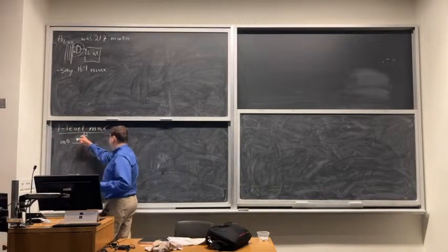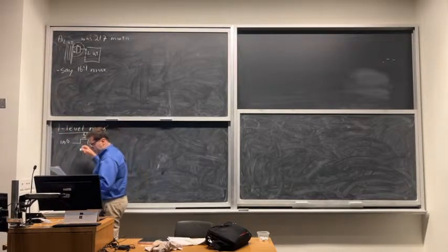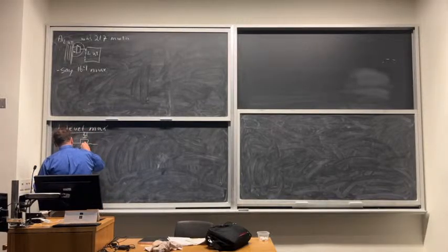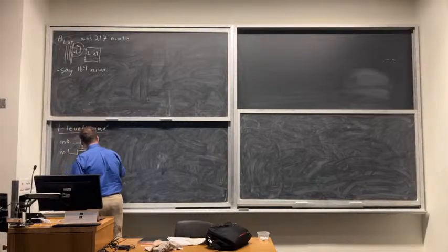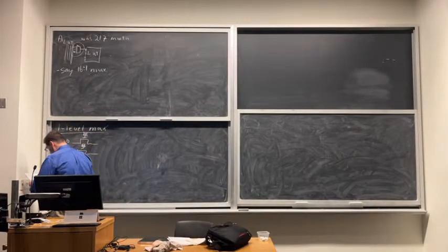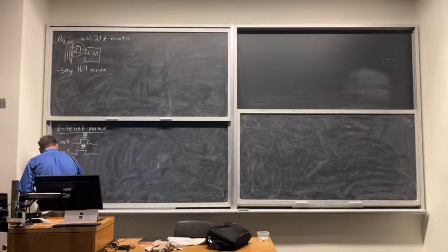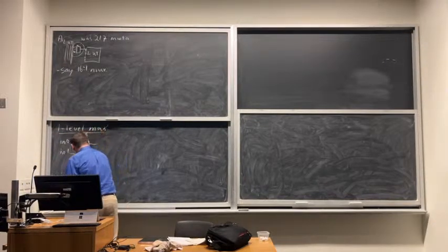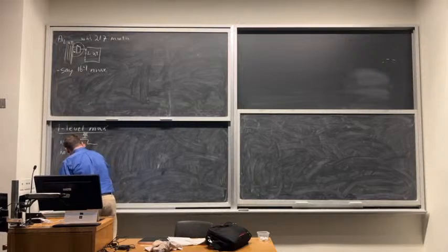So I've got a pass gate controlled by an SRAM cell. Got another input that's possibly connected. Just connect it to a pass gate, another SRAM cell. And I said I wanted a 16-to-1 mux. So that's going to keep going till I get to input 15, which is another pass gate with another SRAM cell.